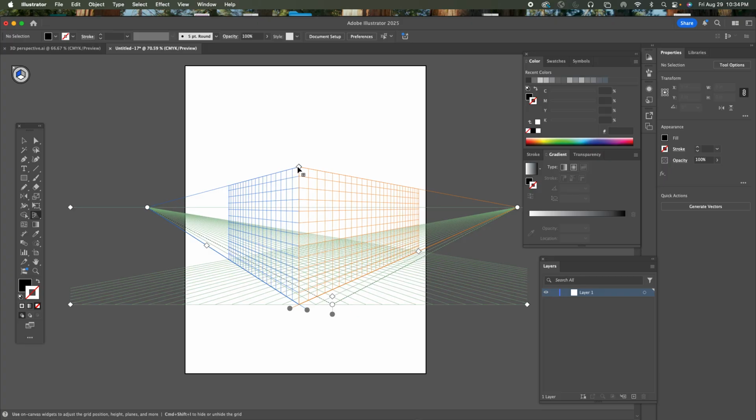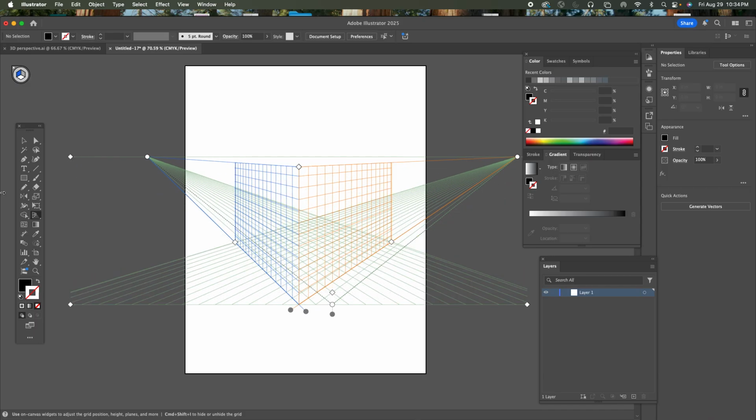Now, let's just draw something basic, and you won't need to draw this, okay? So, let's say I wanted to draw a cube in perspective, and I set my perspective so that my horizon line's way up higher. Then what I would do is I would get a rectangle. I would set my left grid, or I can use 1 as my keyboard shortcut to pick that one.